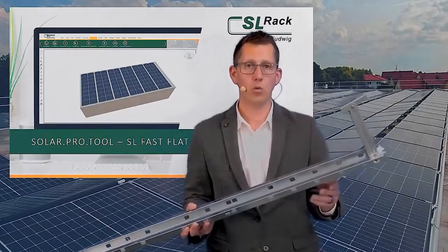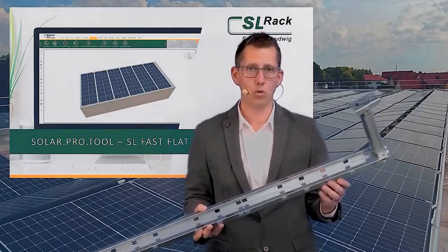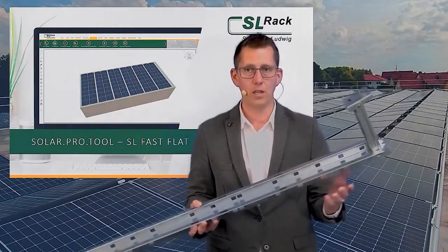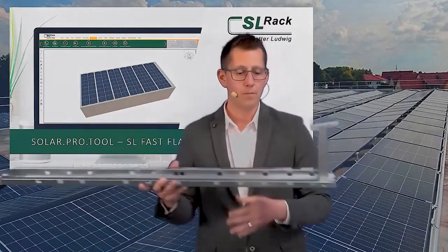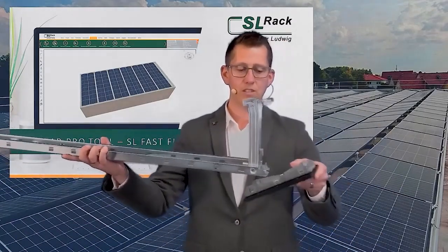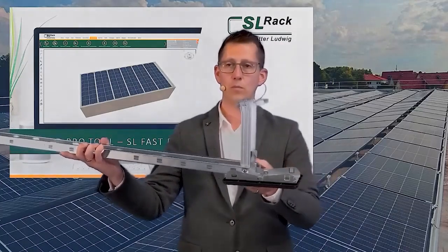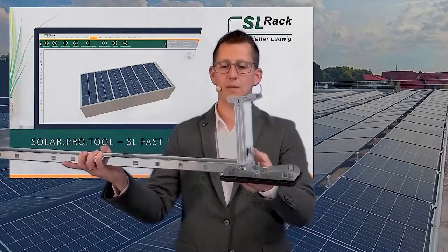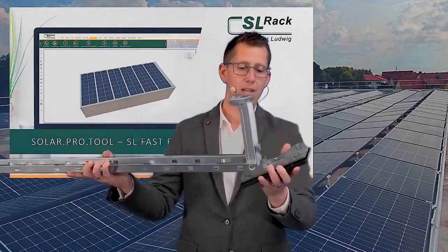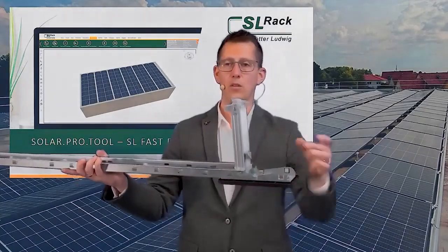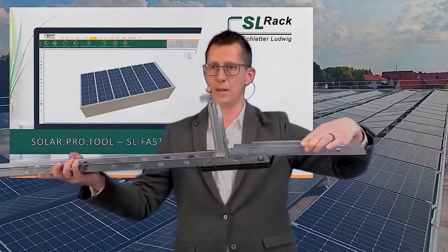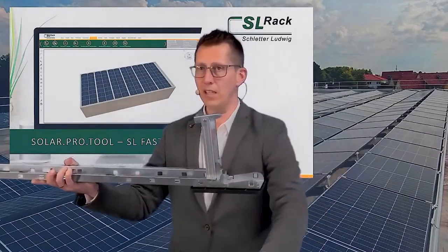Furthermore, here too, a gimmick is added to the Solar.Pro.Tool. I will now mention the keywords ground pressure and soft roof membrane. We will talk about them shortly. The system is designed in such a way that a successor is then positioned at this location, which is a ground shoe. This one is mandatory and needs to be clicked into the system here, otherwise I will have mounted it incorrectly. Clicked into the system here, and then the next rail or an intermediate connector comes here, as per the established procedure for proper installation and alignment.